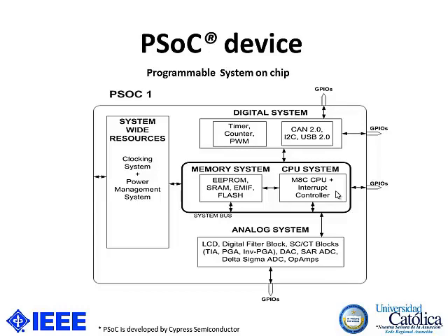So as you can see in this graphic, you can easily configure the digital system to make different kinds of interfaces, for example. If you want a USB port or a serial port, you can do it with that. It's hardware. If you want analog blocks, you have many digital filter blocks, or you have operational amplifiers or different kinds of ADC. And you can connect this easily with the CPU and with the I/O ports.